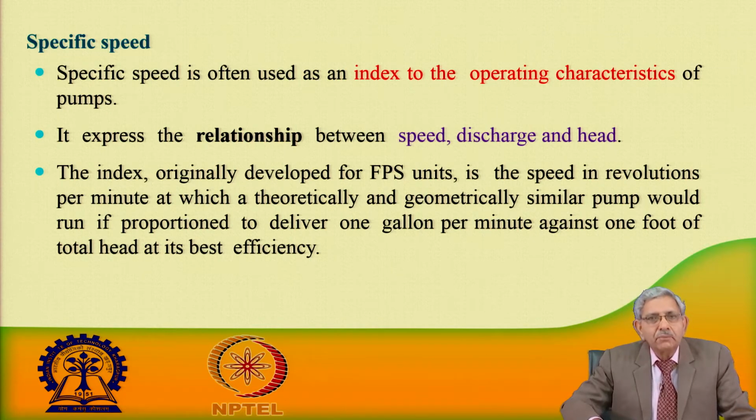When we talk of variable displacement pumps, there are important specific parameters, and one of the important specific parameters is specific speed. Specific speed is often used as an index to the operating characteristics of pumps. It has an interrelationship between speed, discharge and head.